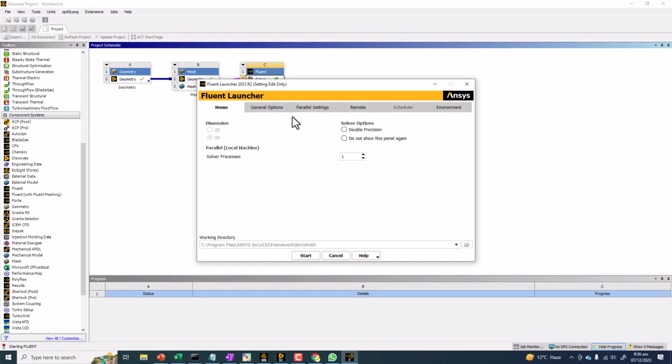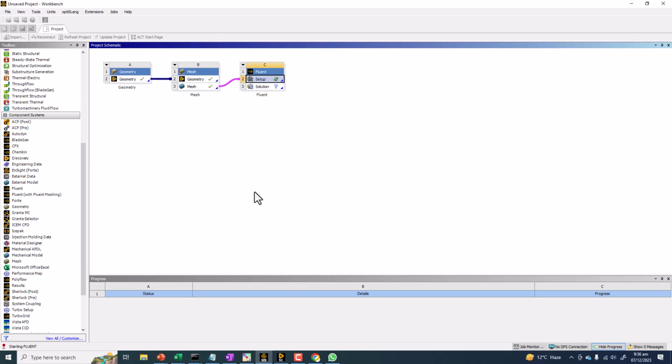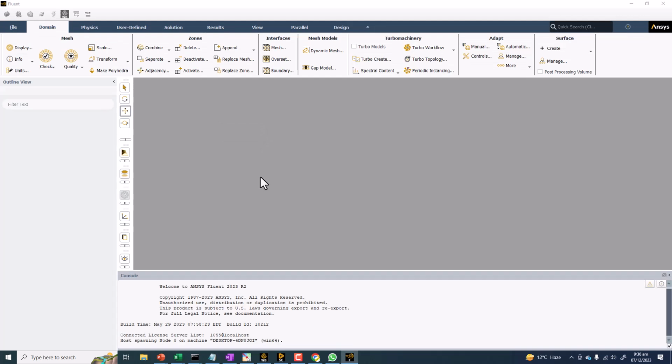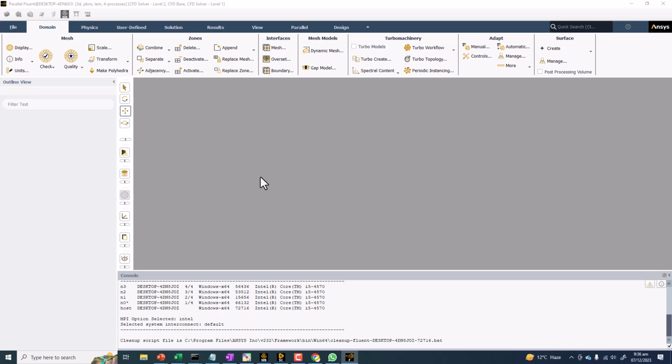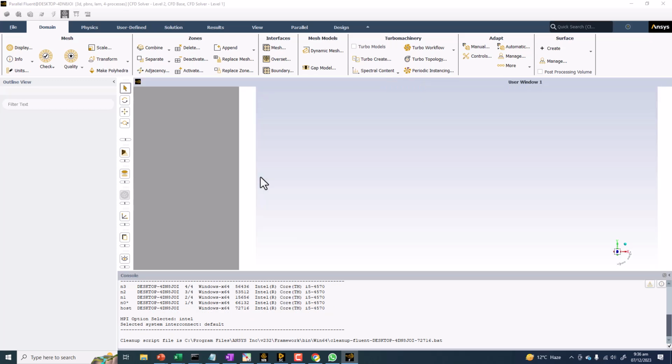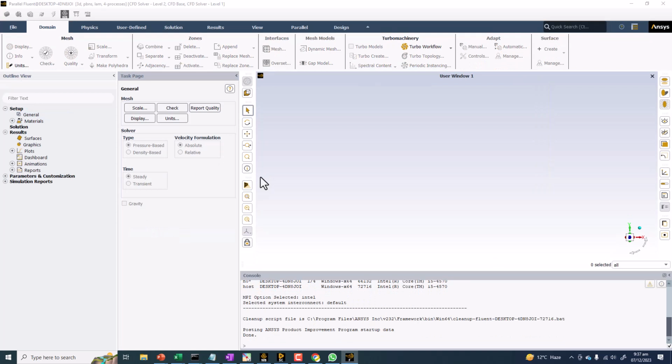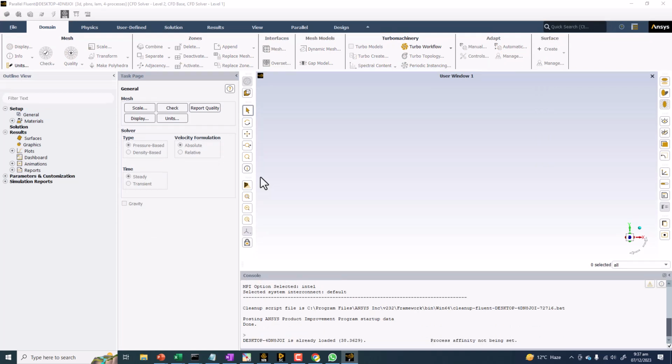This will open the Fluent setup, and you can use multiple processors, for example 4, and click on start. If you have more than 4 cores in your CPU, or maybe 2 CPUs like in workstations, you can use them. The rule of thumb says that for at least 0.5 million cells there should be 1 core, and better would be 1 core for every 0.2 million cells, and for every 1 million cells around 2 to 4 GB RAM is required.